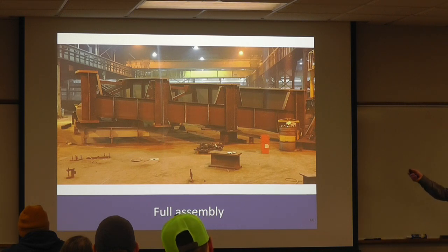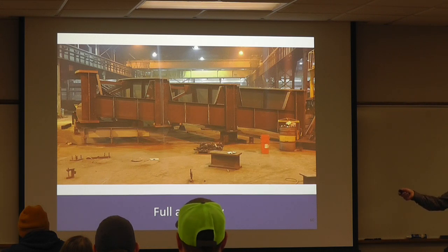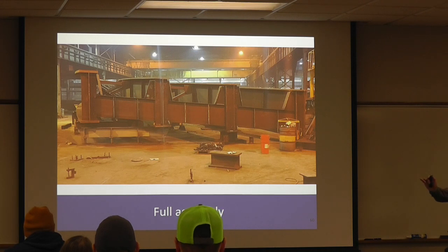And so you can see this bridge is both curved and super elevated. So the contractor needed to block it in its super elevated position, because now they're going to take every one of these diaphragms and they're going to put them up on the steel and they're going to drill them from the blank. So diaphragms typically will not have the holes formed in them. The stiffeners already will. So they'll bring it together and they're going to drill them to fit in that exact configuration.